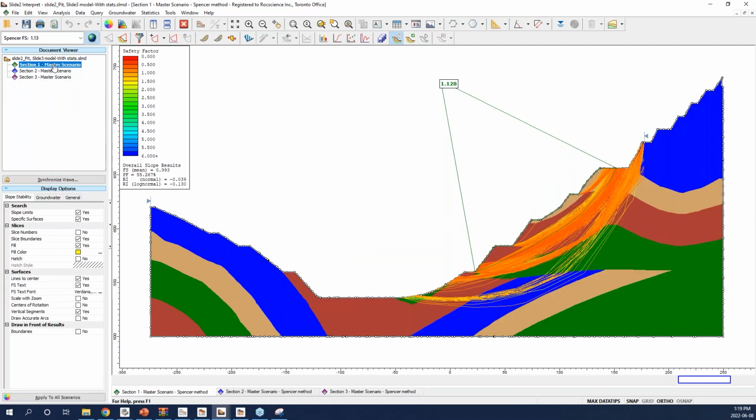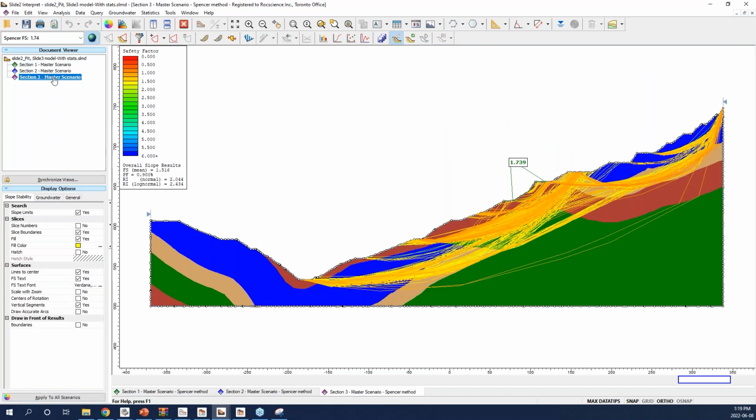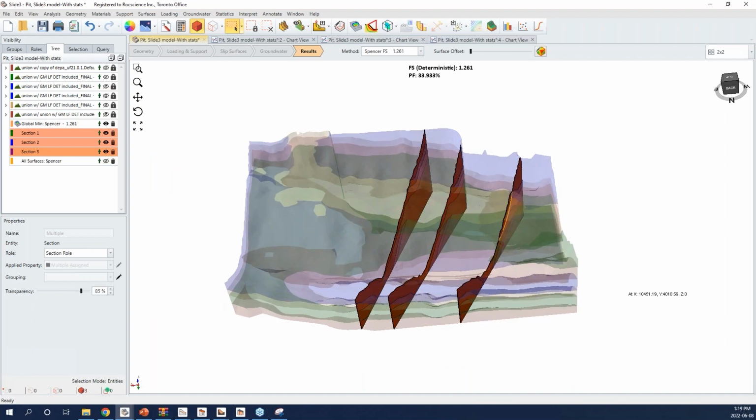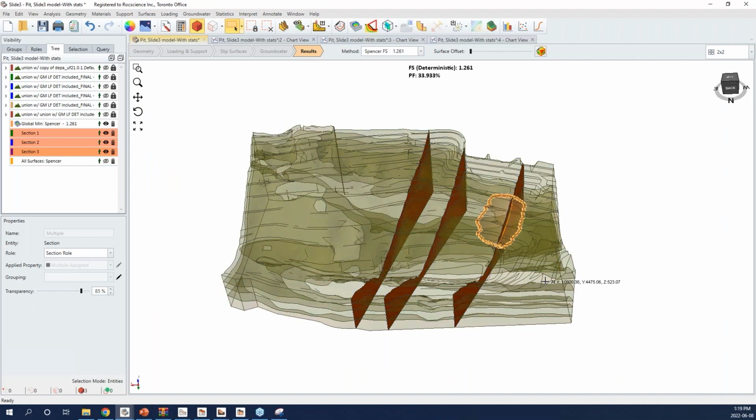And now that you have one more parameter to compare between 2D and 3D, you can see that the probability of failure changes from 55% to 0.9%. So which one of these 2D sections represents the 3D model? That shows the advantage of doing 3D modeling for more complicated models like this, to get a proper factor of safety and now a proper probability of failure.